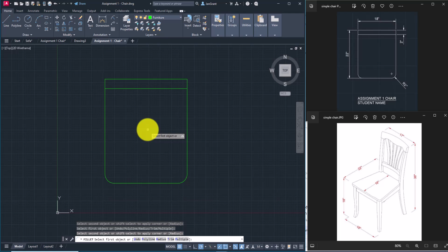Where we are going to learn a little bit about scale factor here too, because this is a big object. I'm going to use the escape key to get out of this. This is a big object. This is potentially bigger than a sheet of paper. So it's not a 1-to-1 scale. We're going to keep everything in model space 1-to-1, drawn at full scale.